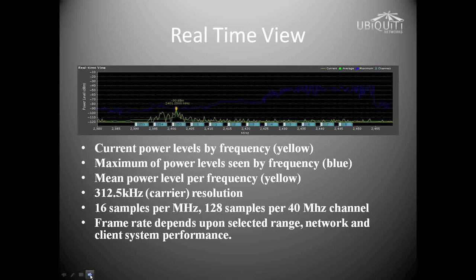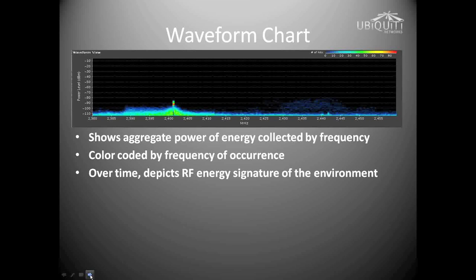We normally show it in person, but with this real-time view here, you'll see this line jumping up and down as it's detecting different types of RF carrier signals. One thing to note, this detects all RF radiation, not just 802.11 based sources. So it'll help you find if you have electrical lines, microwaves and that kind of stuff interfering with your devices.